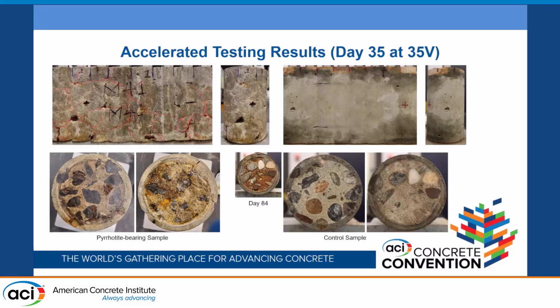The protons migrate to the sodium hydroxide end, and we believe hydrochloric acid is being formed on the sodium hydroxide end. Hydrochloric acid is known to be used to separate aggregates from the concrete matrix. So we believe that's what is eating away this part of the matrix.